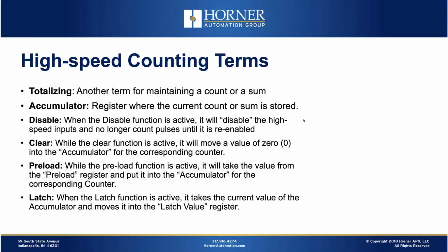And the last one that can be useful from a function standpoint is a latch. So very often we might have a free running counter that's counting time ticks or something like that. And when a very exact type scenario hits, a certain signal turns on, we want to latch the value in the accumulator and then access it on the next scan with whatever the value was at that instant. So a latch function, which is sometimes called a strobe function, is another term that we'll be talking about.